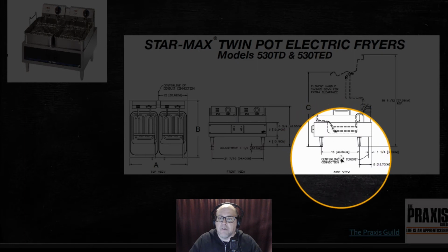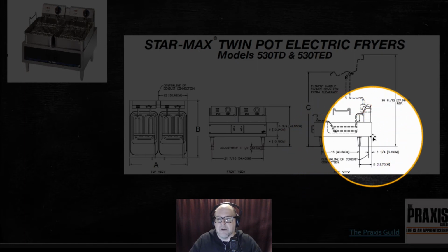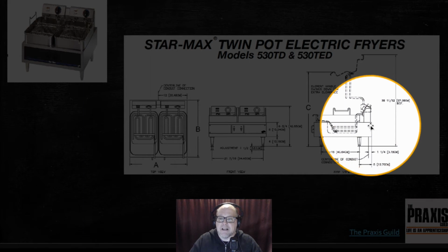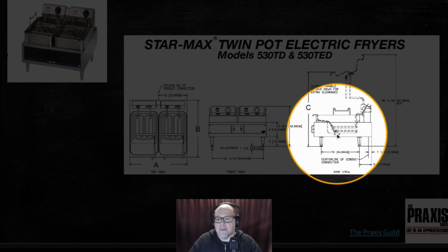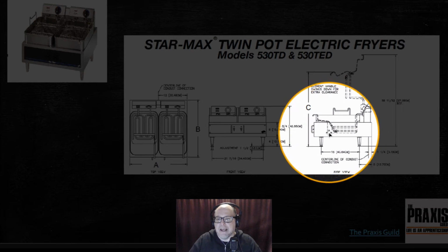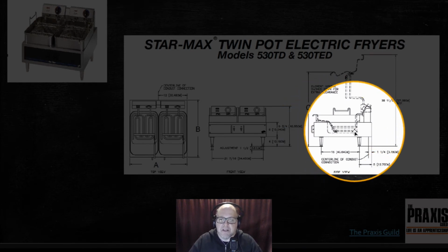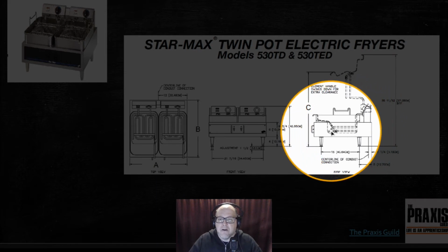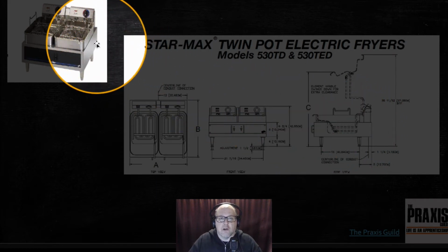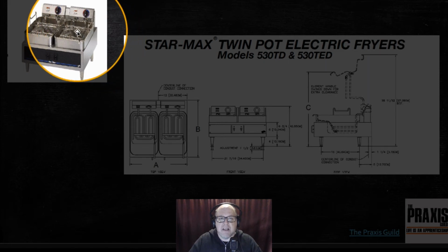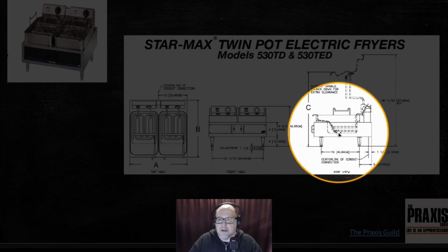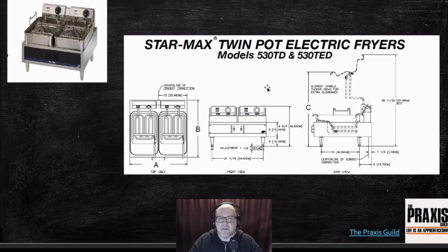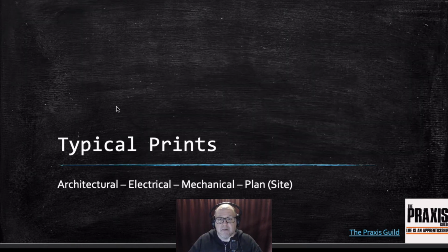And then over here, they call this a side view. Again, they're going to show you some different aspects of this piece of equipment in the side view. Most importantly, you can see that these dotted lines indicate what's going on inside this piece of equipment. You can't really see this when you're standing over here looking at the piece of equipment from here. You can't see this stuff inside because the outer casing blocks it. But on the drawing, they indicate it by a dotted line so that you know what's there. That, in essence, is what some specification sheets may look like for a piece of equipment.